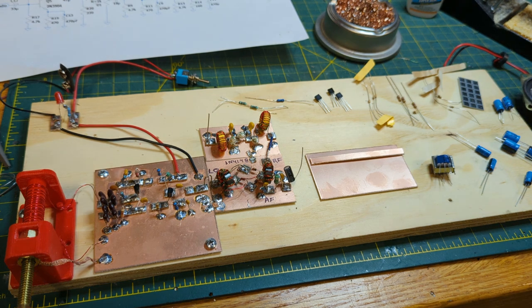But if you don't have that and you have trouble figuring out which one is the primary, just measure the end 2 pins on each side with your ohm meter, and the primary side is going to have a resistance somewhere around 56 ohms, and the speaker side will have a resistance of somewhere around 1 ohm. Now those are DC resistances, so they're not going to match the 8 ohms and the 1K that you expect, but that'll give you an indication of which side goes to the transistor and which side goes to the speaker.